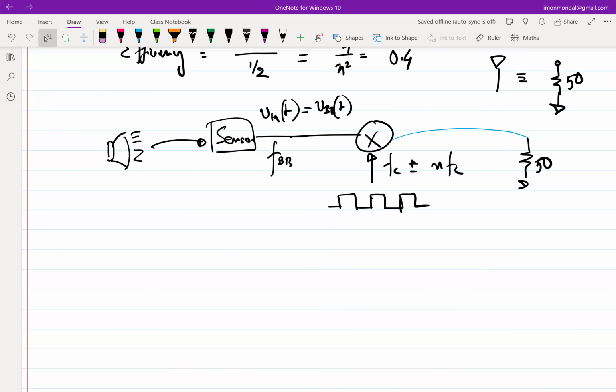If you want to transmit video, the bandwidth required is of the order of a few tens of megahertz, and can go up to hundreds of megahertz, depending upon the fidelity of the video. So the moot point is you have specific frequencies in which you can transmit. You cannot transmit anywhere else. You cannot say that my mixer generates n·fc, what can I do? Not possible, right? You'll get to court.